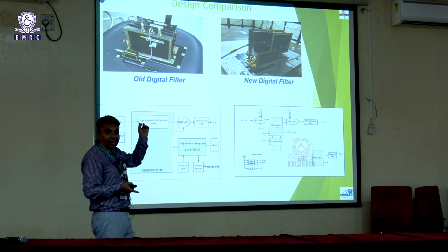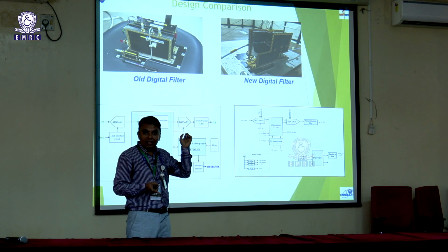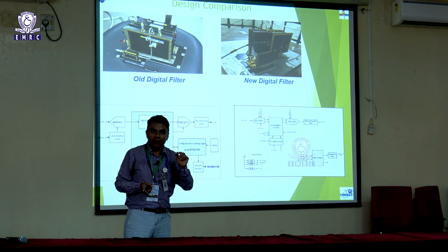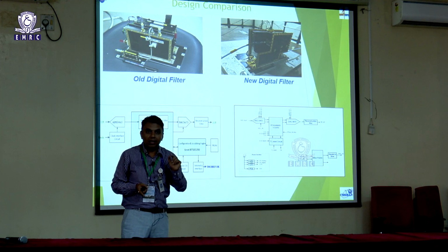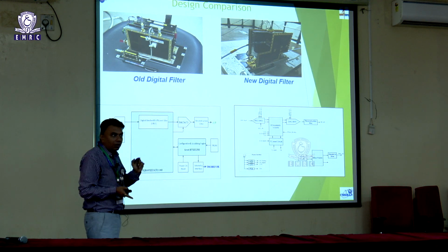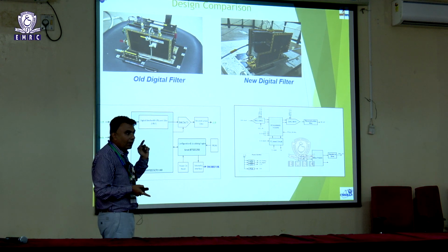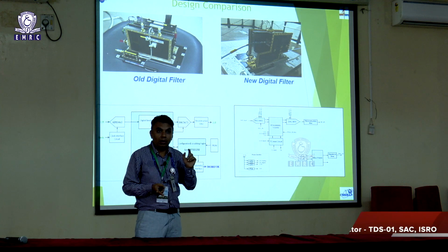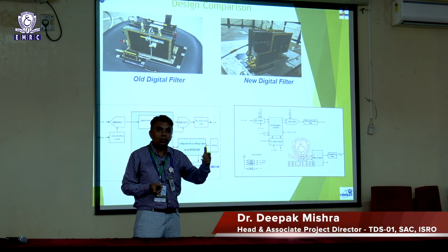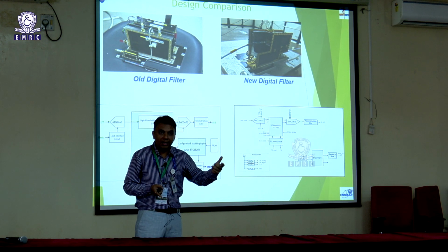The earlier satellite I discussed, with the digital filter, is on a Virtex 4 design. We used Virtex 4 for the design of the digital filter. But once the satellite reached space, we found some radiation issue with the Virtex 4. Sometimes we need to reset the design.